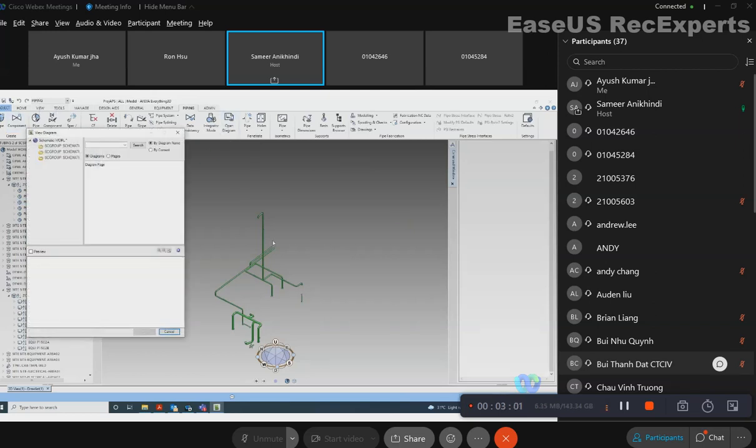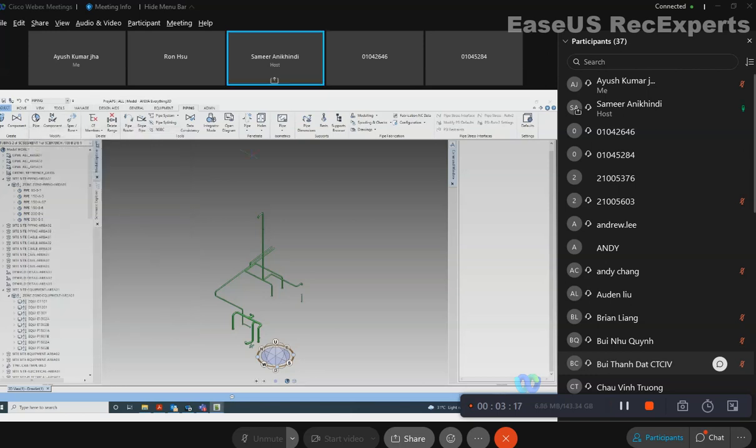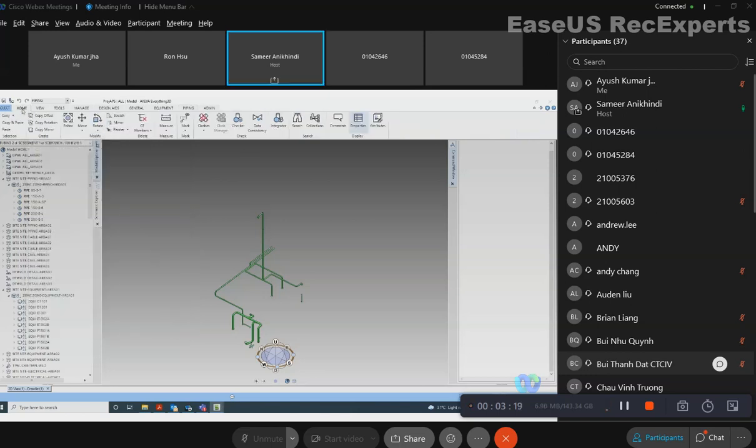Normally, I tell you the way is you have to just right click on the pipe in the PNID and it will give you the build option. It will give you the build option only if the pipe is not there in the model. Remember, if the pipe is already in model, it will give you just the compare option. But let's do this way for just to view.